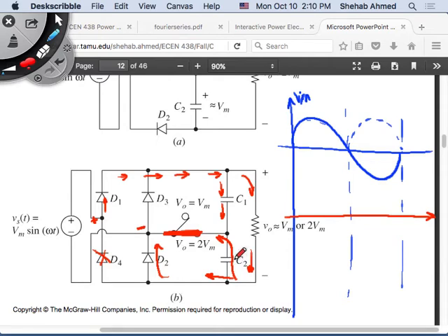So the current will have to choose either to go through this large impedance or go through diode D2, right? So depending on the value of the capacitance and the value of the forward voltage of the diode, the current will go through this or that. That's only in the initial transient, but in the second half cycle, so this is the positive half cycle.